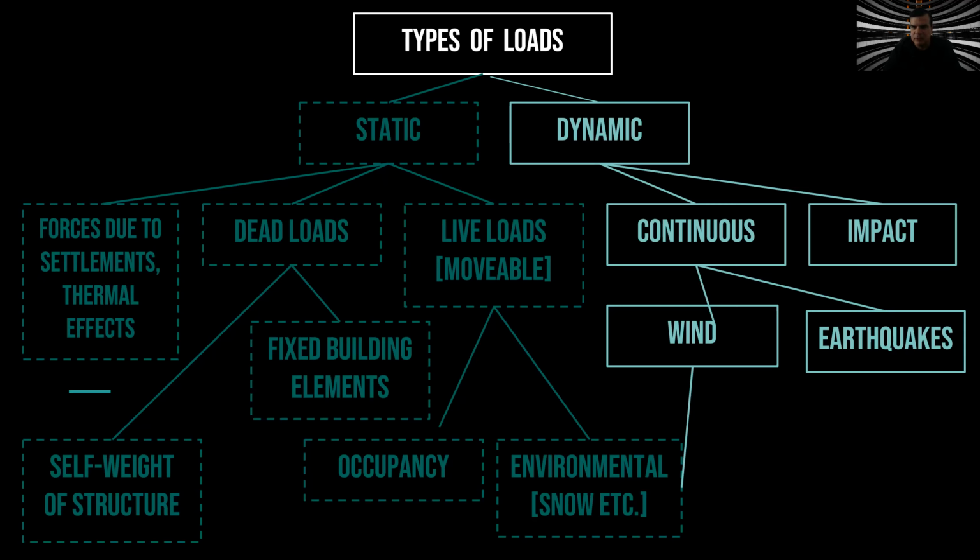That is very important to understand because in the building codes, we are speaking about two main loads that will be dead and live. Dead is everything that is fixed in the building, the self-weight. Live, all the things that move in the building. We will look at them a little bit more carefully later on.